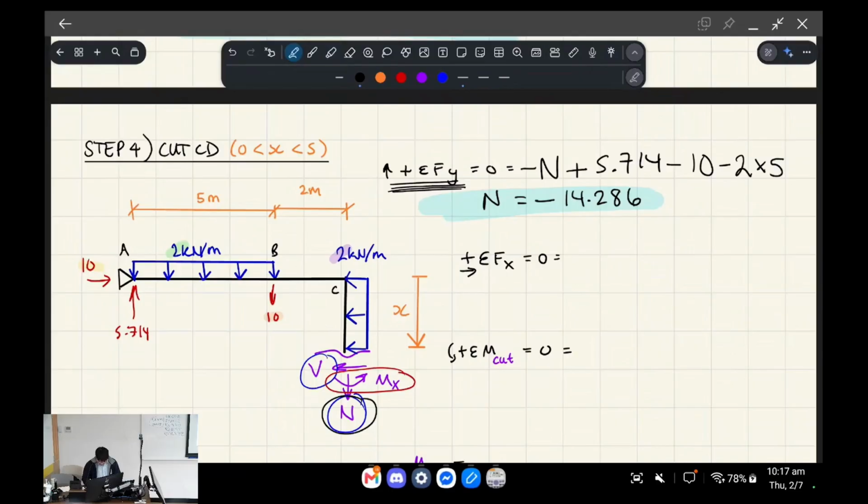What you're going to see is that the shear force is pointing to the left. So we're going to do negative V, right, because we're taking the horizontal sum, with pointing to the right as the positive direction. And then we're going to add on 10, and that's due to the horizontal support reaction.